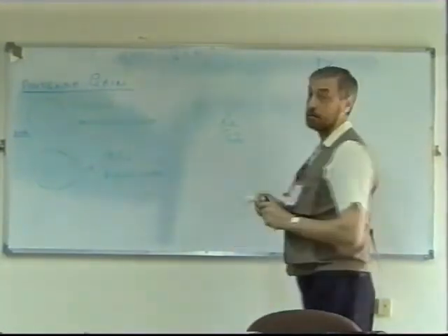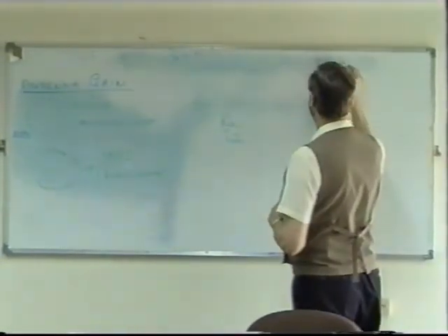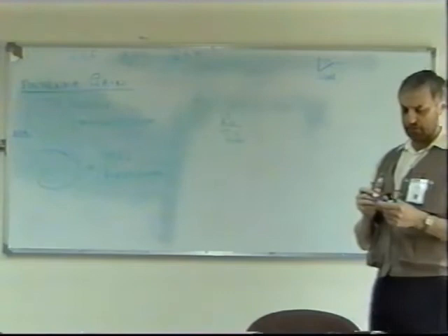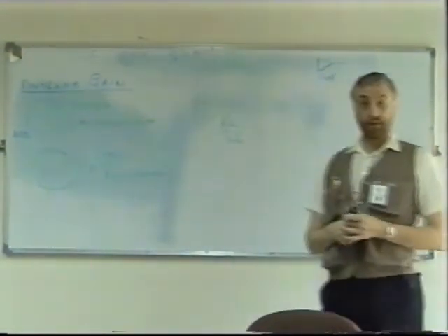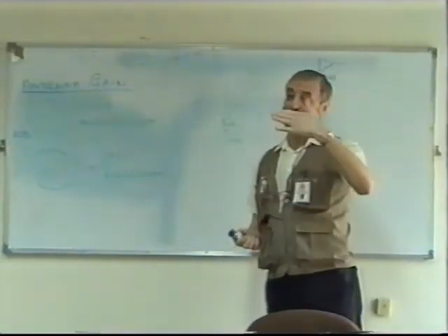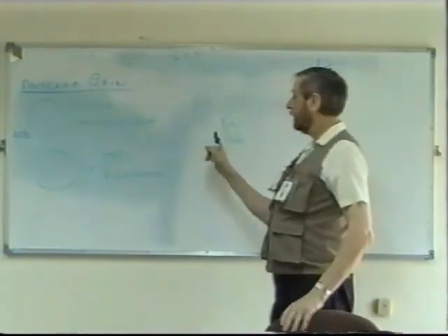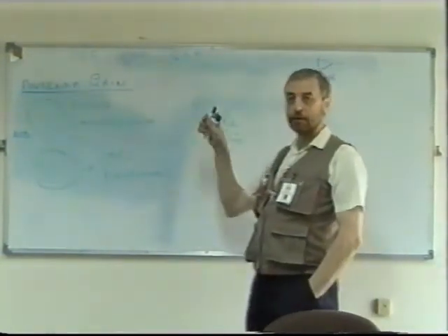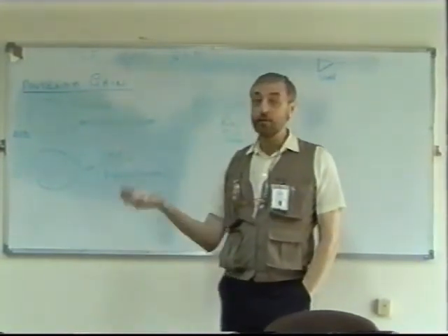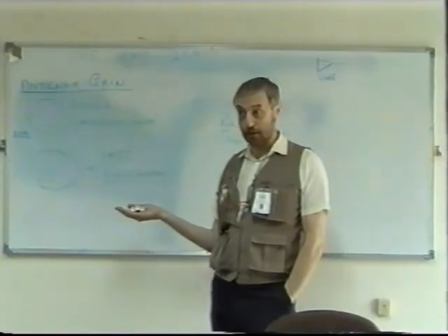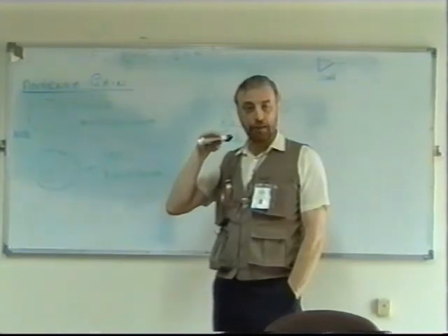You get much more noise. Ah, now we're bringing, that's the word I wanted you to use. The word is noise, isn't it? Remember, we're dealing with radio signals here, and it's important that we can receive the radio signal above any noise. So if at the receiver antenna here I get a weaker and weaker signal, eventually, remember noise is generated all the time in any communication system, and radio is no different. Eventually the signal will go below the level of the noise.